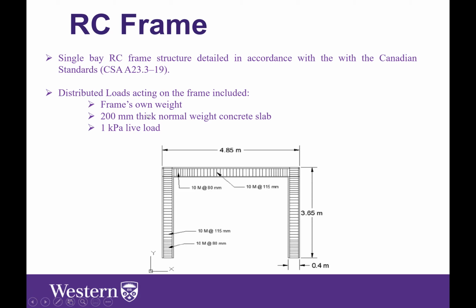As you're going to see later on, we studied the effect of the beam span by modeling spans of 3 meters, 4.85, 7, and 9.7 meters. The steel reinforcement was adjusted for each span to maintain the same demand-to-capacity ratio, in order to give us a more consistent comparison.